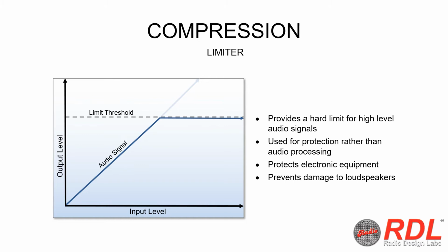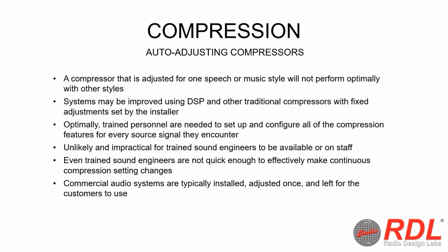A compressor limiter uses both effects together to form the ideal combination of signal control and a barrier for equipment protection. All source signals can benefit greatly when compression is applied with the correct threshold, ratio, speed of attack, and release for each signal type. A correct configuration or setup will produce very natural sounding yet controlled audio signals. The wrong setup will produce very unpleasant artificial sounding results.